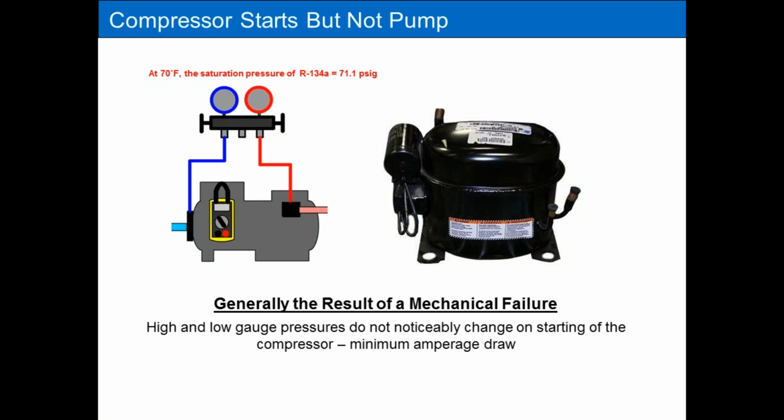When you do that, I'm going to recommend that you measure both your suction and your discharge pressures. A lot of guys just troubleshoot by looking at the suction pressure and not the discharge pressure, and that could lead you down a very dangerous approach. Your suction pressure is not the only thing you need to be looking at. If you want to troubleshoot these units properly, look at both suction and discharge pressures, and that will avoid some common mistakes that we'll talk about coming up.